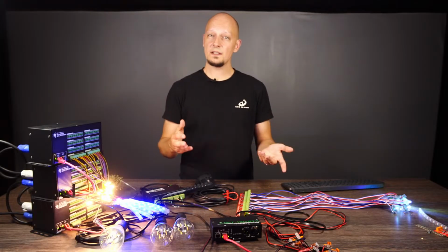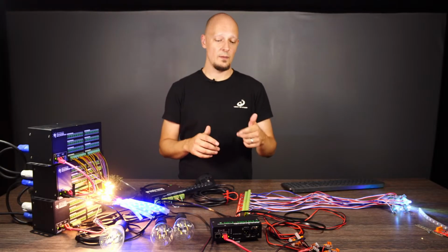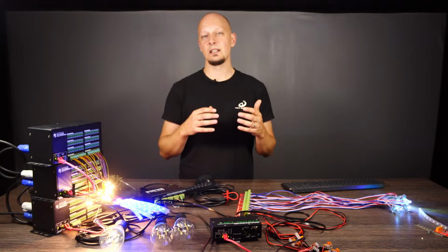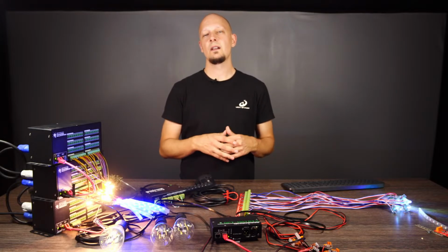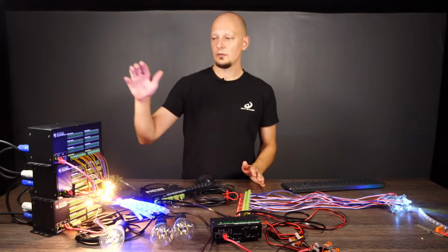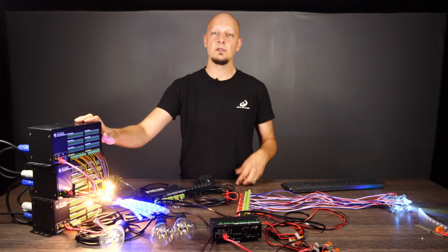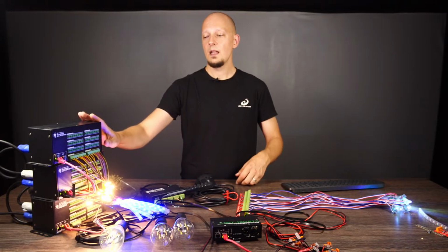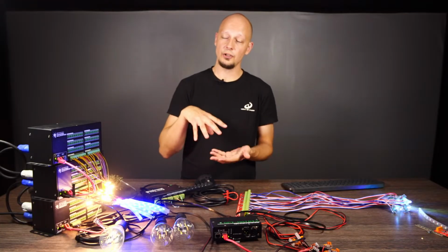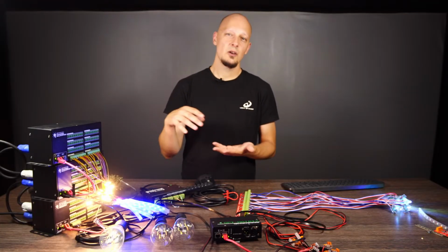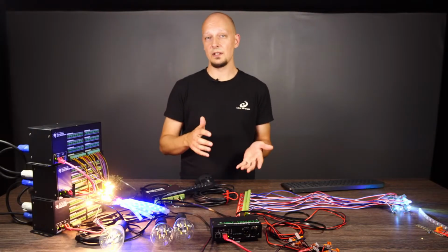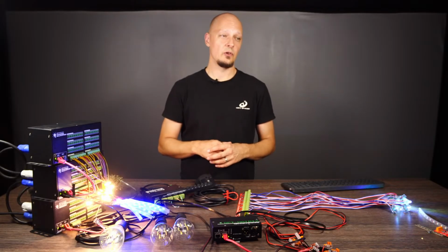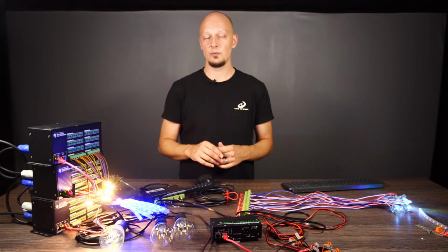And once again, as with SPI lamp or the pixel shifter, we are sending out differential data, so the distance from the controller to your dimmer can be very, very long. We are talking hundreds of meters. If you are not sure whether it will work on your specific project, on your specific distance, we can always have a mock-up here and test it. Or you can send us a sample and we can test whether it will work properly for your project. So don't hesitate, just reach out to us.